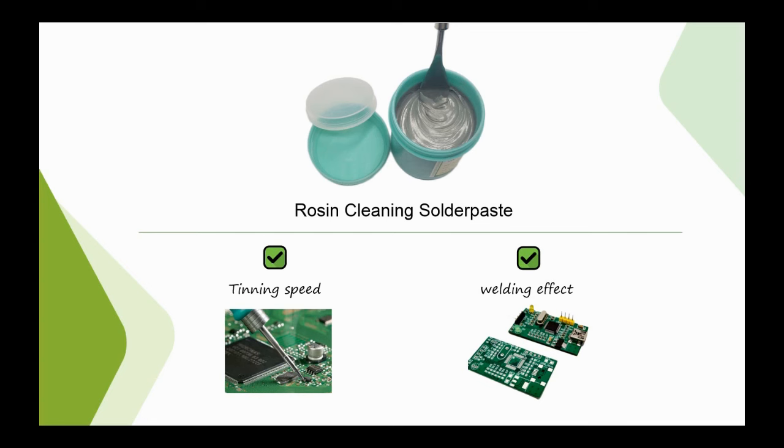After work is finished, the PCB's surface has more resin residues. The worker can clean it with detergent and the PCB will be shining without any residues, which guarantees the PCB has good insulation resistance and various electronic properties. Technical tests will be passed.